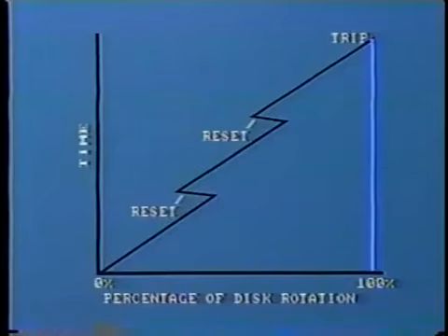If a repetitive fault occurs, the disk may not have time to reset completely, and each repetition may cause the disk to creep forward, and so after 2 or 3 repetitions, ultimately trip. These limitations must be borne in mind when calculating relay settings.